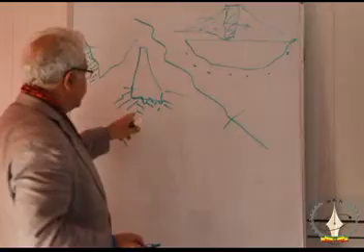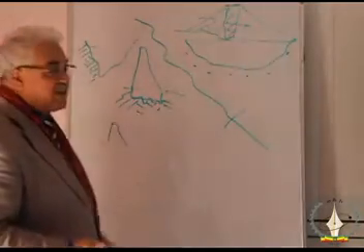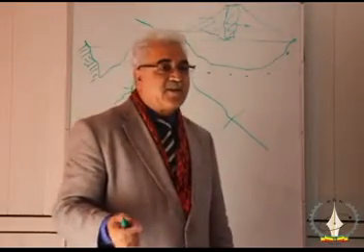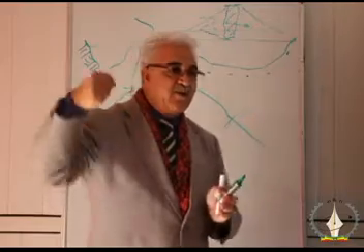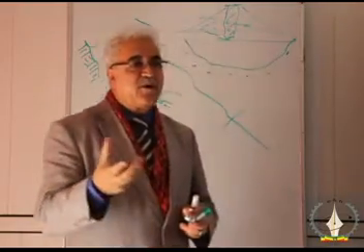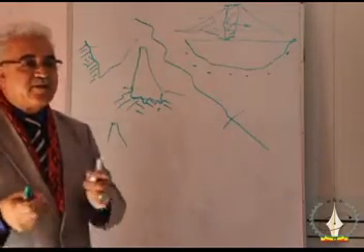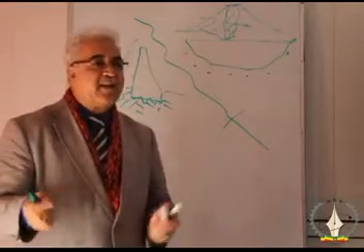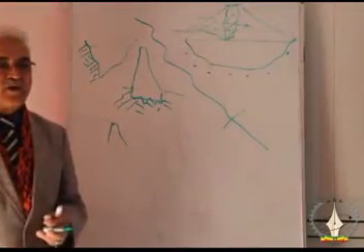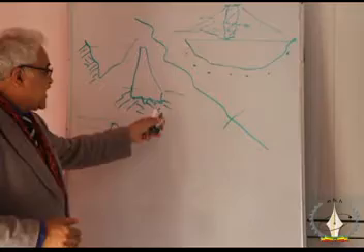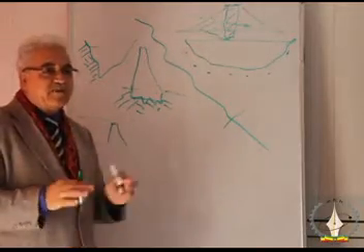And if there are some cracks or anything here, they will grout it. Grouting means that you push some sort of fluid, cement and clay and other types of material, with high pressure into these cracks to make sure that everything is blocked.